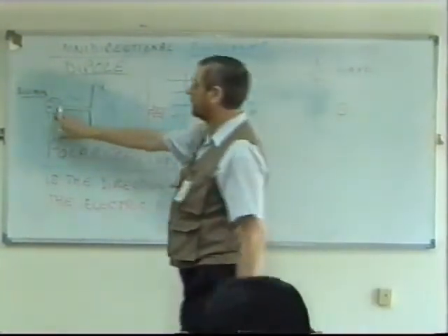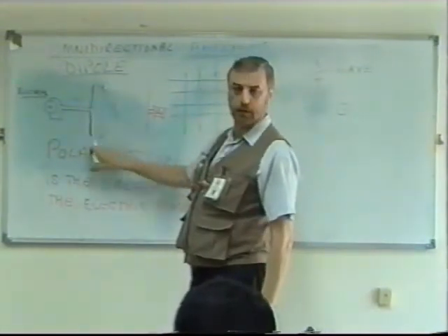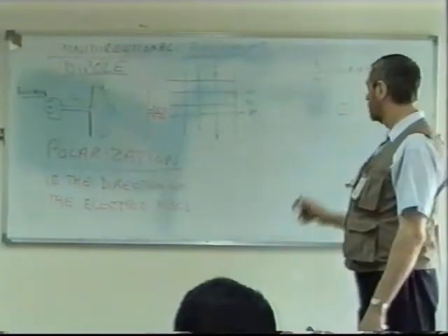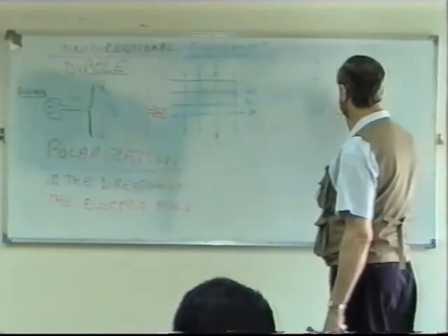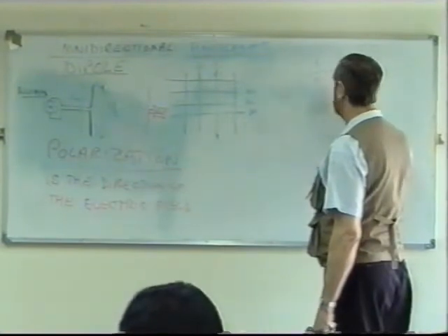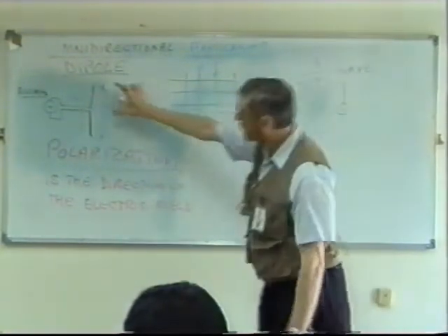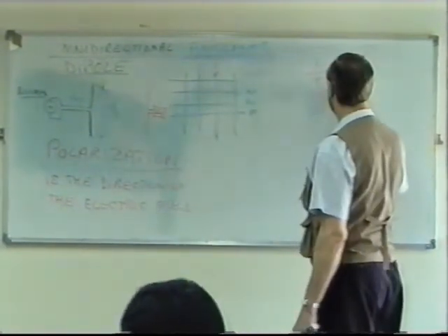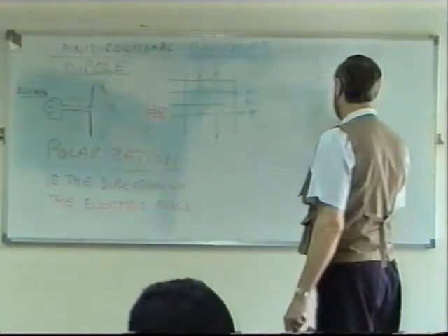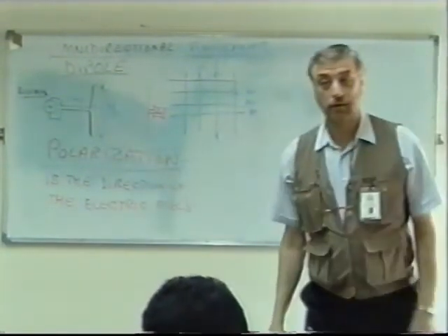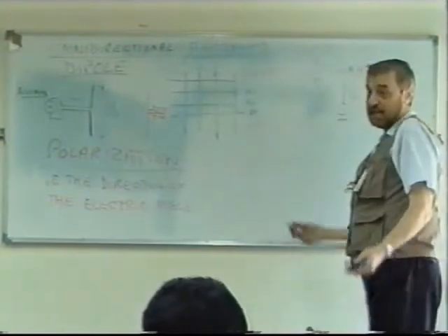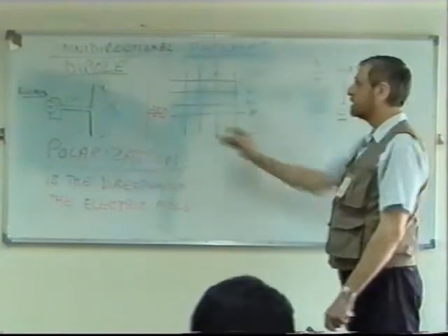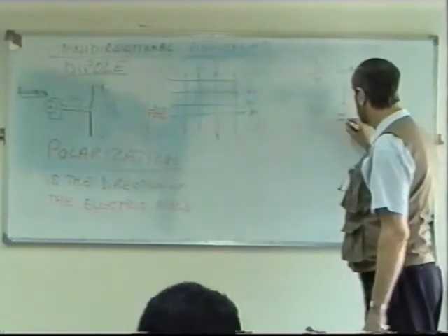on our dipole, we connect our oscillator to the middle of two conductors, the total length of which has to be half a wavelength. What Marconi found out was if he connects one end to only half of this, see, this half here is a quarter, and this half's a quarter. So he connects this to a quarter wavelength, and he connects the other end to ground. Then, basically, he's got more or less the same characteristics as our dipole. It's called a quarter wavelength.